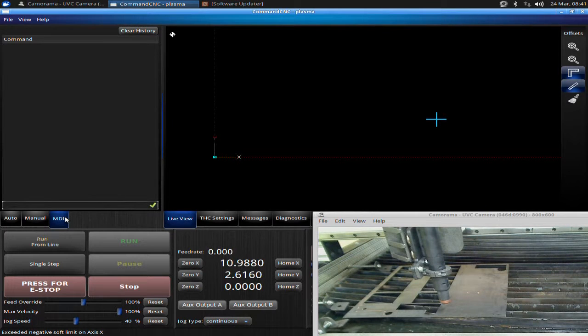So there's a lot of resources out there on how to write G-code and reading G-code and whatnot. G-code's not rocket science. It's pretty straightforward. So I'm going to just show you a few brief ways to make the machine move around so that you can precisely position the machine where you need it to be. So let's say, for instance, bring the torch down. We're going to 0 my X, Y, and Z here. So let's say that's my job 0.